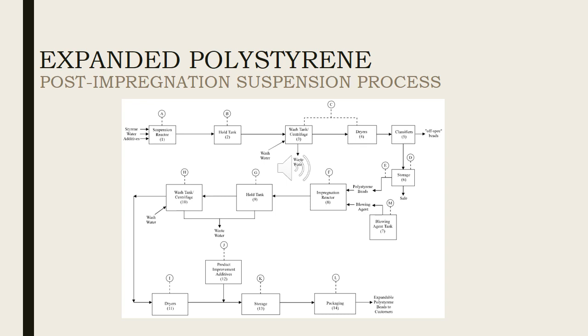From the hold tank, the polymer water slurry is fed into a centrifuge, which is unit number 3, where water and solids are separated. The solids are then washed with water, and the wash water is separated from the solids and is discarded. The polymer product beads, which may retain between 1 and 5% water, are sent to a dryer, which is unit number 4.